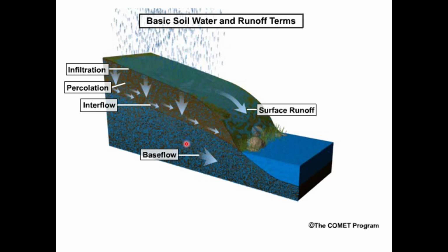And here is another example, a cartoon of groundwater discharging to a river and causing base flow. So we're going to see more of that in talk number 2, base flow. There's also a term here, interflow. It's a little oversimplified to say that if the water infiltrates, it will then recharge groundwater. A lot of times what happens is it'll infiltrate and then stay pretty shallow if the slope is steep, and then it'll seep out the banks and contribute to the stream.